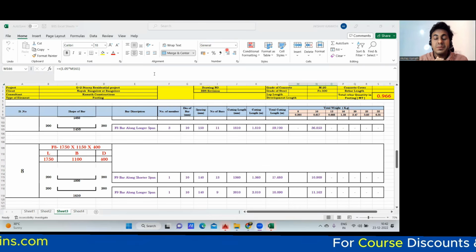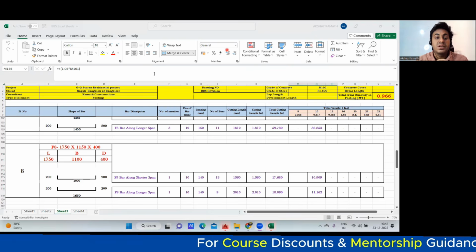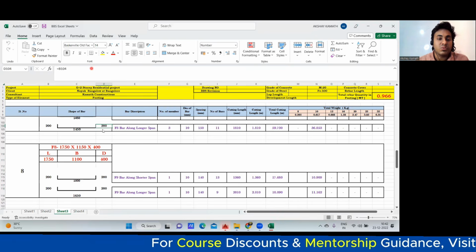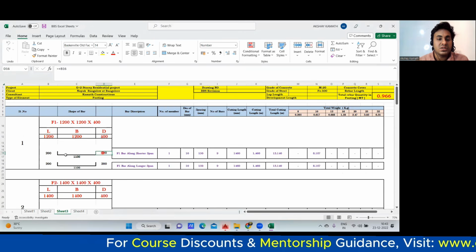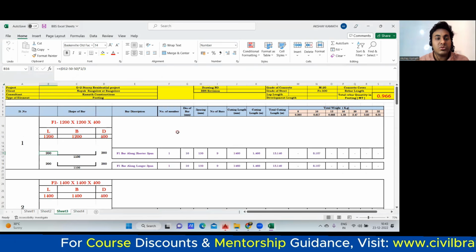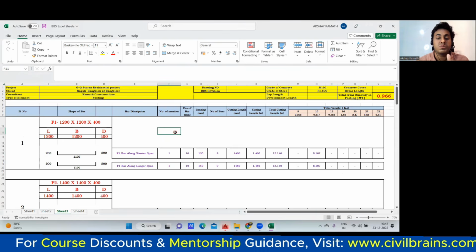So in this lecture, let me clear few of your doubts. Whatever I have taught you so far in the BBS, you may have few doubts like when we should consider the bend deduction, when we should not consider the bend deduction. Then in few of the cases, I told you this depth, you have to take 2/3 of the depth, right? Here, if you remember, we have taken 2/3. In some of the cases, I told if it is not required, not to be taken. Now, when do you use such cases? I'll give you complete information here.